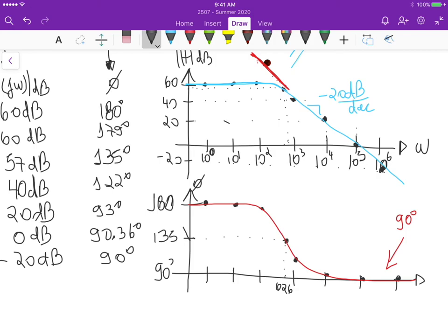Okay. Now, for the last part, which kind of filter does the circuit implement? So if you look at the drawings that we have here for the Bode plot, for lower frequencies, we are actually amplifying by 1,000, right? So over this region here, lower frequencies, we are letting things be amplified. But once you go to higher frequencies, especially at this region here onwards, we are attenuating.